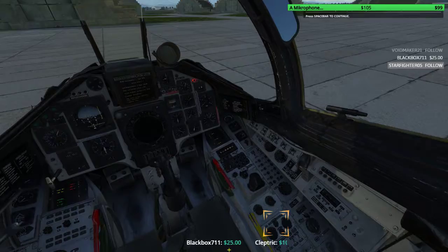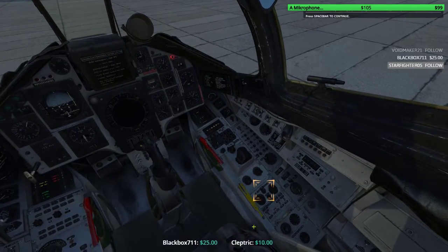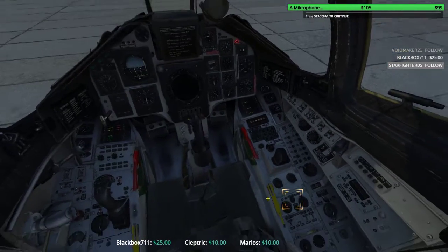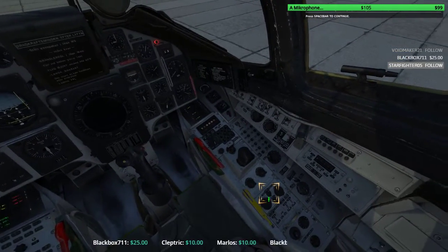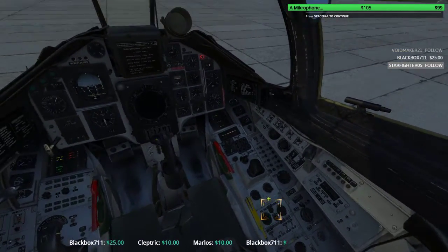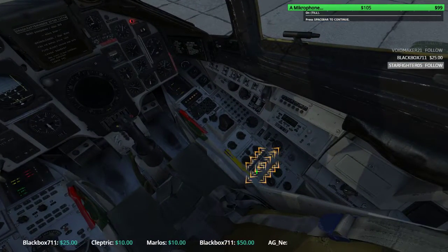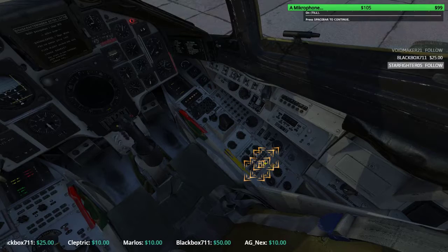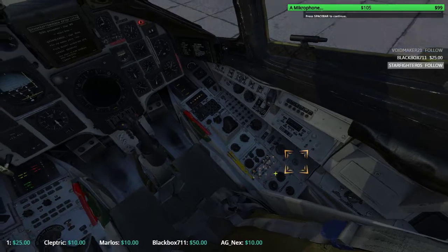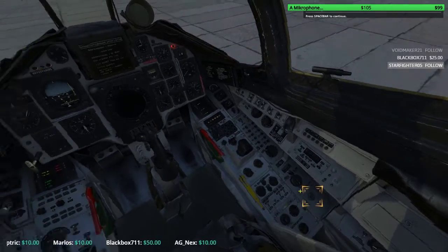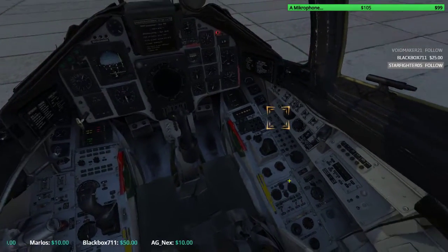Set the radar warning receiver to the desired position, either off, lights only, or lights and audio. Now turn on the external lights. Set the navigation lights to full. Confirm the setting or set the local magnetic declination, which in turn turns on the radar altimeter.